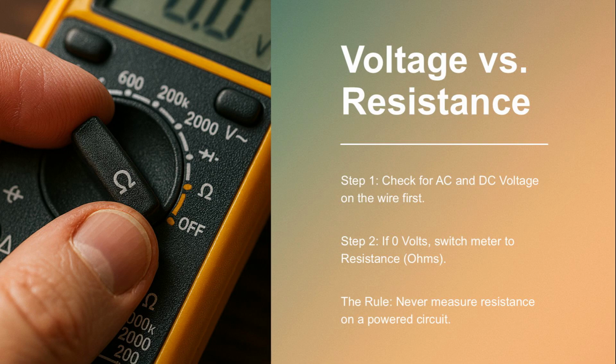Once the grounded circuit is identified, use your voltmeter to start testing. First, check for both AC and DC voltage on the wires. If no voltage is present, then switch your meter to resistance testing. Measure the resistance between the conductors and ground. If you receive a reading below 1000 ohms, chances are you have located the circuit containing the fault. The lower the resistance reading, the closer you are to the actual damage.